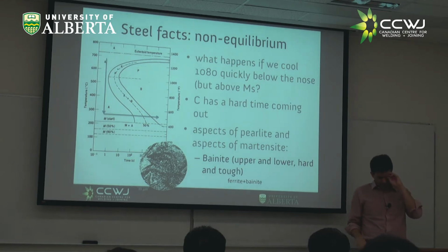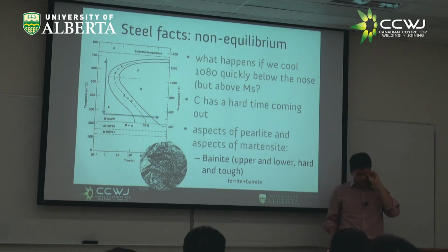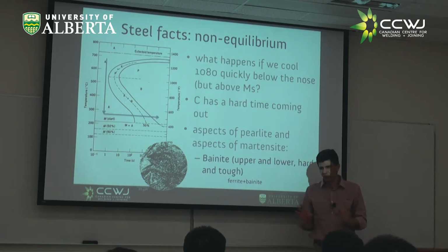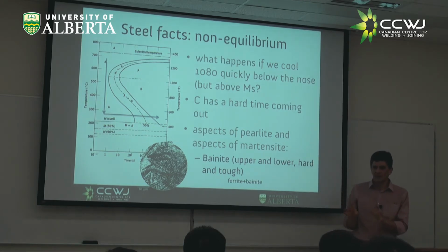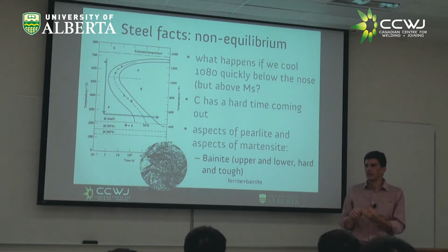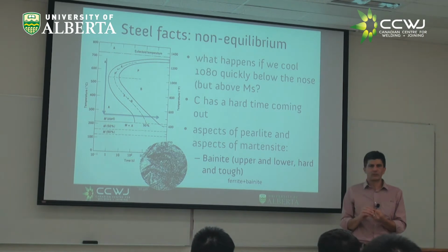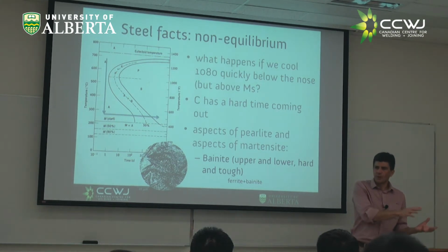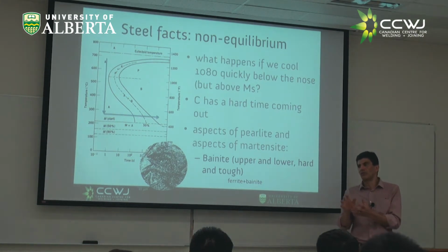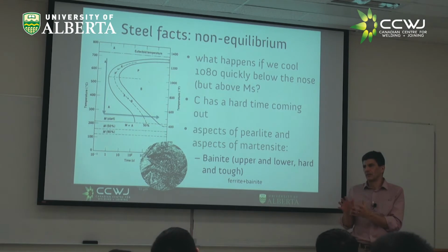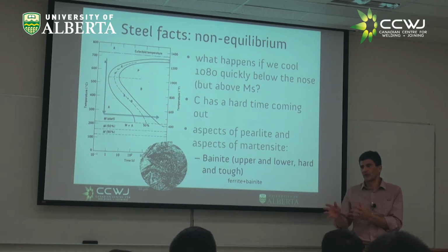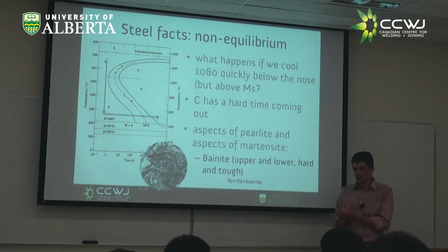Well, people have gone into incredible arguments about what bainite is, so I'm not going to get there. But I can tell you something. In bainite, you have diffusion, and you also have displacement. So bainite is some kind of combination of what we know of martensite and what we know of all the other transformations in which the carbon is diffusing, right?